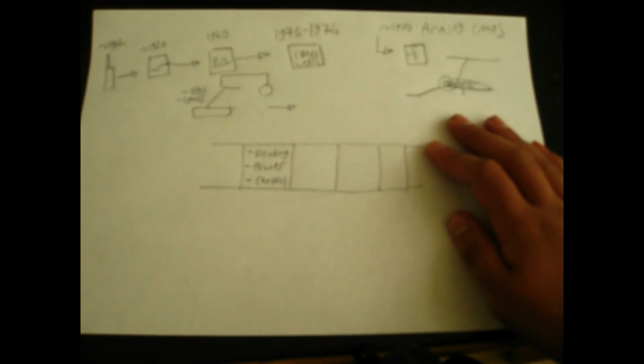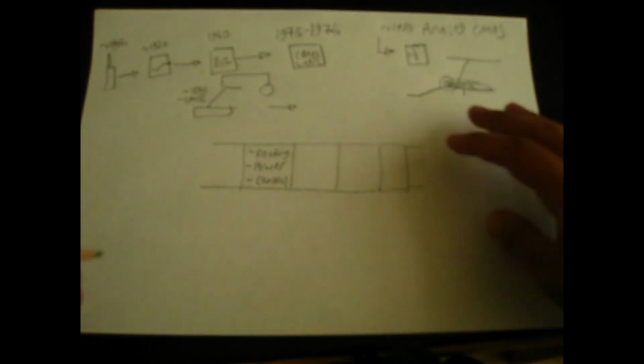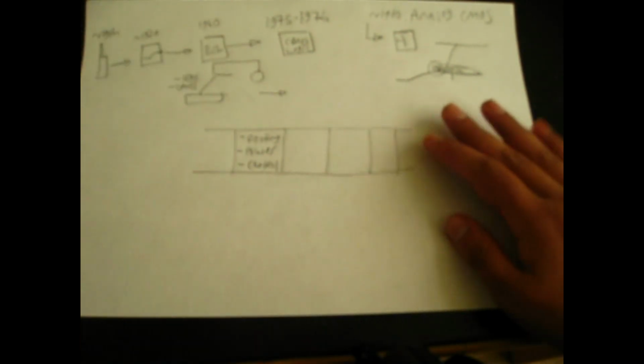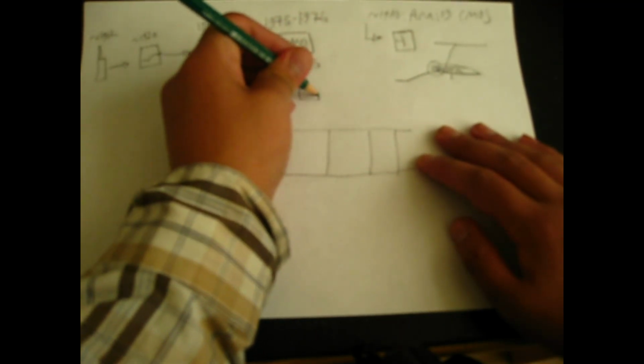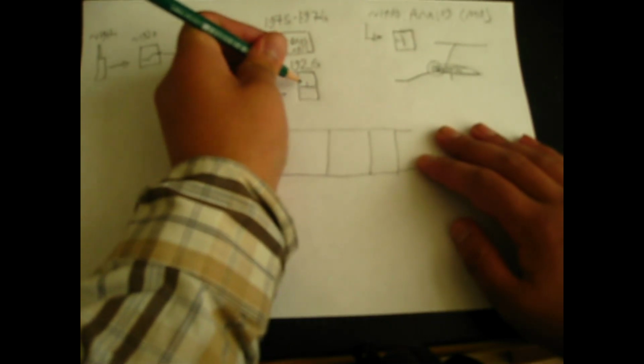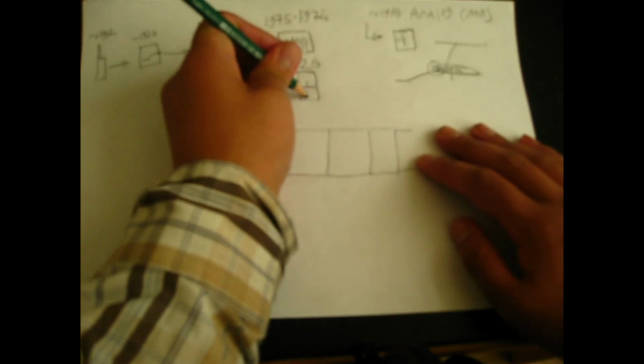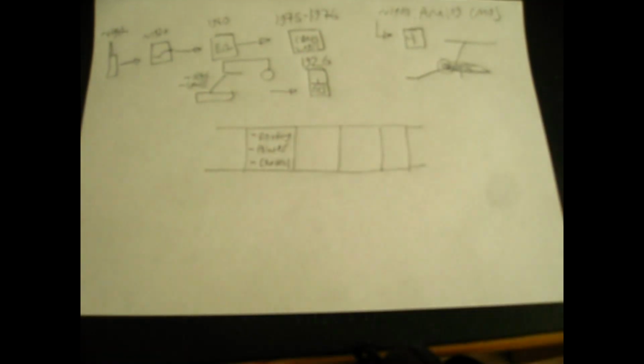I don't know about that, because there's a lot of different systems for train control. But here in the Netherlands, the most important milestone is 1926, with the introduction of pulse code cab signaling, or PCCS. This is actually an electromechanical system where we use pulse code based relays to determine the signal aspect and display it to the cab driver, and in the event that the driver overspeeds, it would stop the train.